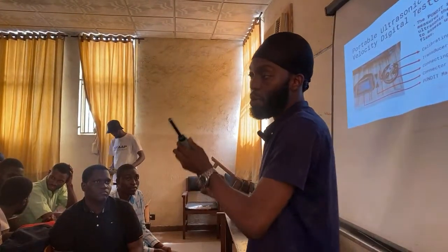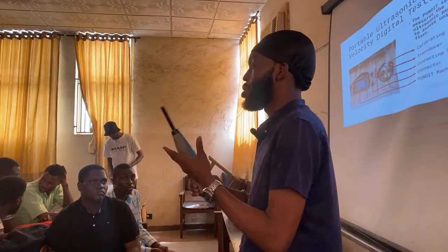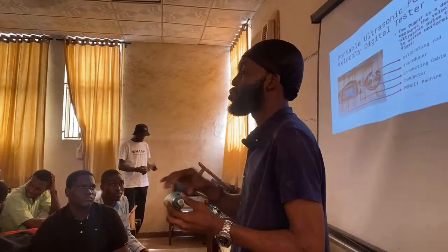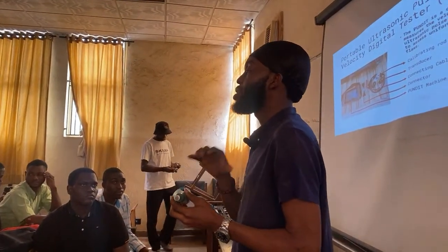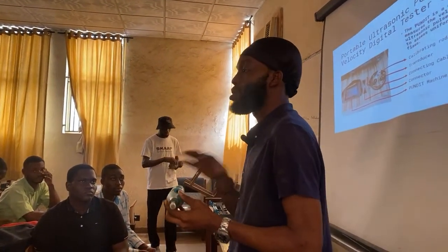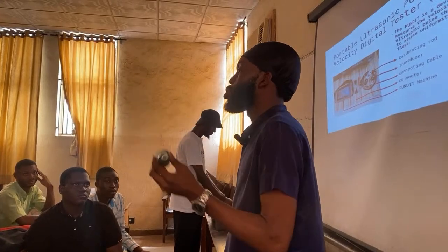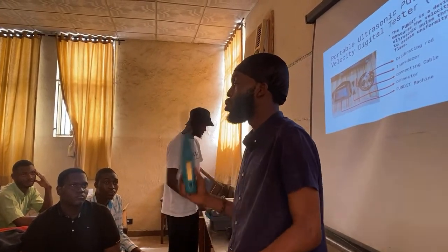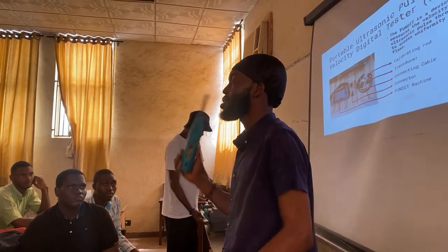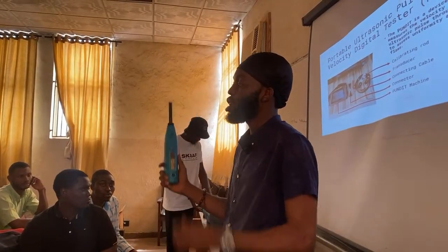So there's a factor of carbonation in this Schmidt hammer. But mainly it is used for concrete surface alone. Rendered surface, it's a no-no. Any finishing that is done on a particular concrete surface, you cannot use the Schmidt hammer again. So it's only when the construction is ongoing and all the structural elements are still exposed that you can use your Schmidt hammer.